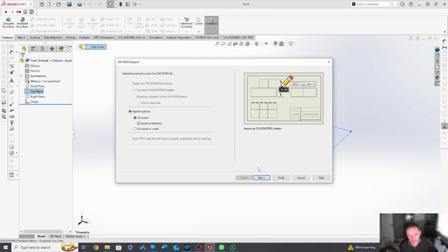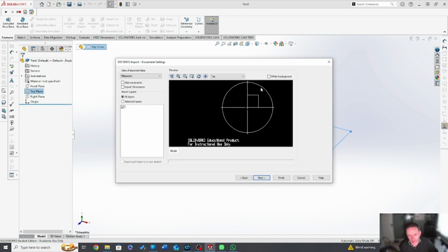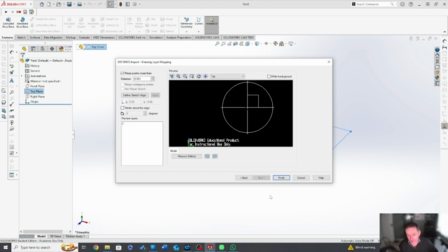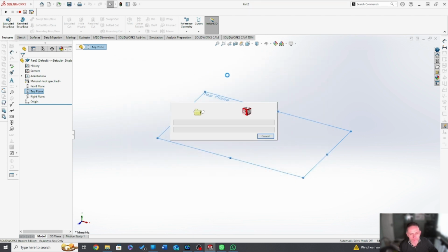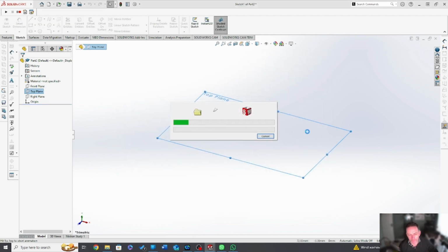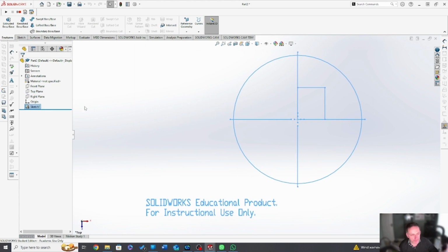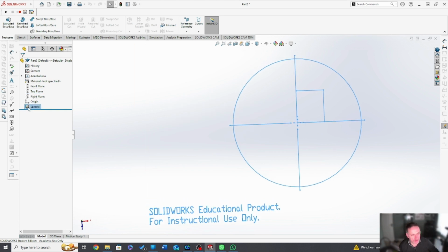So what I'll do is go to my import from a two-dimension, then go OK, and then it sees this as a piece. Is that what I'm after? Is it in millimeters? It is, and it is. So I'll click next, and then it asks me about overall referencing. Where's it all going? Merge points closest, which is fine, and then I click OK. 3, 2, 1. And there it is. So you see there where it's got this little warning sign through it.